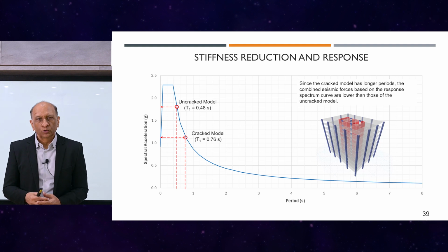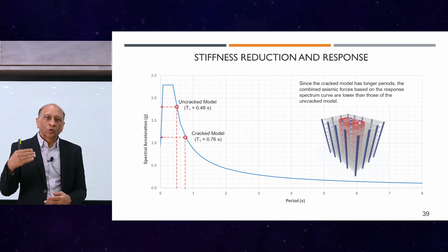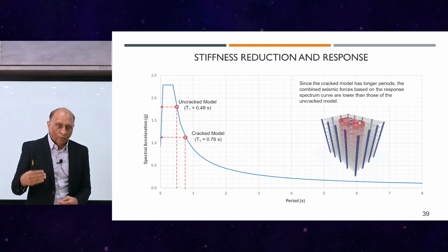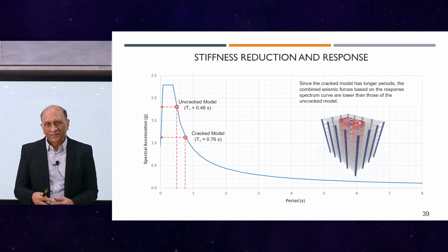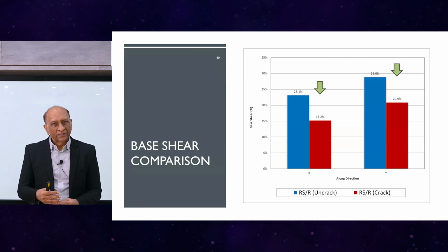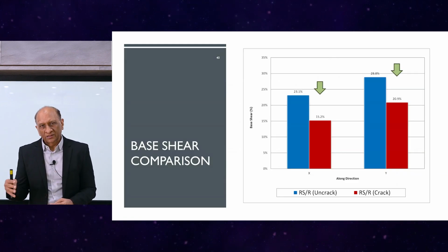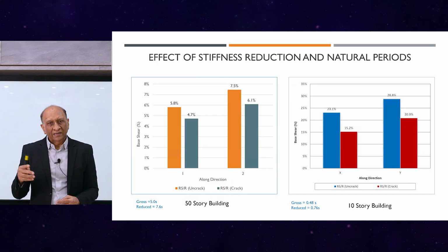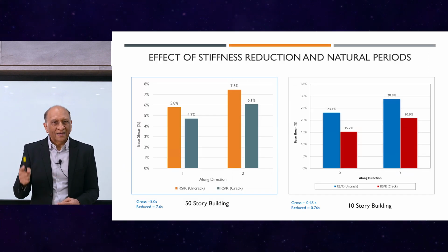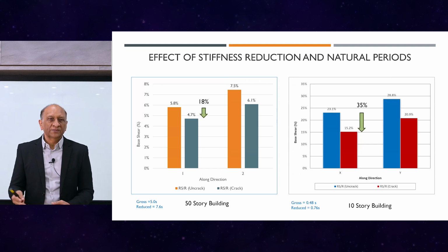You will have roughly 2 to 2.5% damping as the starting point. 5% is the code-specified damping, normally used for concrete buildings, especially low-rise buildings, for design purposes. And then 10%, 15% damping happens as the structure deforms, cracks and degrades. And like I showed you earlier, we have the cyclic energy dissipation. The damping keeps increasing, so it can go up to 15%, even 20% or more.